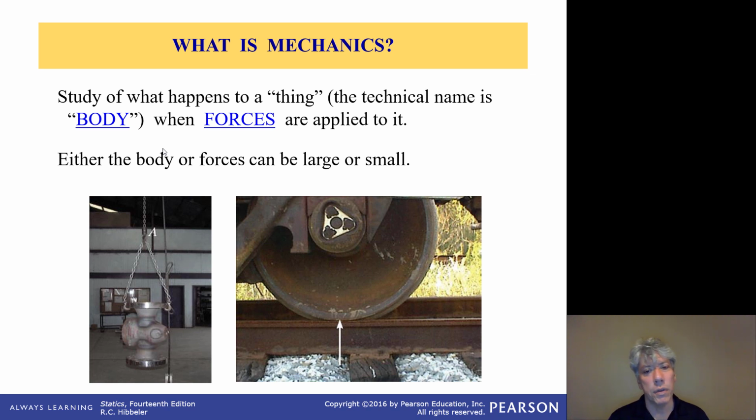And so we're always interested in forces applied to points, when in reality, most of the time forces are not really applied to points. If you think about the rail wheel there versus the railroad way, you'll realize that if you were to apply all of the force to a single point, so it's a curved wheel, that's a whole lot of force over a very small area, and that means a very large pressure, right? Because pressure is just force over area. And so what would happen is actually the bottom of the wheel, where it's curved, it would have to go flat, at least somewhat flat.